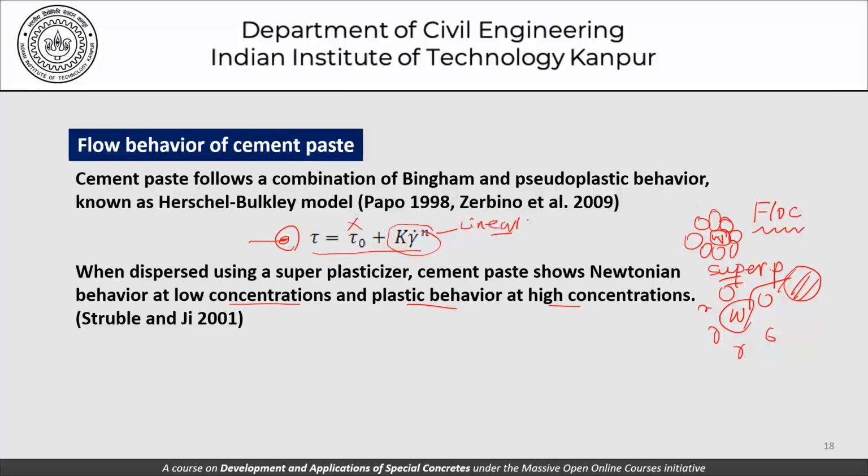Now in the present context, what is being said is that if this water becomes available here, even though the solid concentration still remains the same, because we are not changing the cement content per se, the cement paste would become Newtonian, would tend to show a slightly higher tendency for segregation. It would become a more Newtonian fluid, show lower levels of yield stress than in the case that